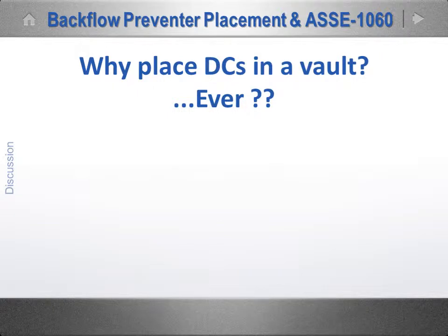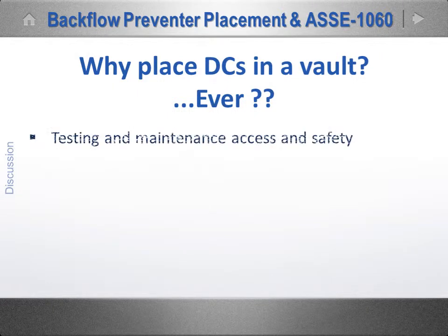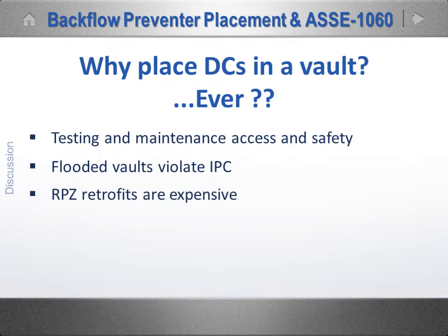So here's the first hard question. Why a vault? Ever? There are testing and maintenance access issues, as well as safety issues with vaults. Flooded vaults violate the International Plumbing Code, and if that vault-deployed double check ever has to change, RPZ retrofits are expensive and they're usually not very pretty.